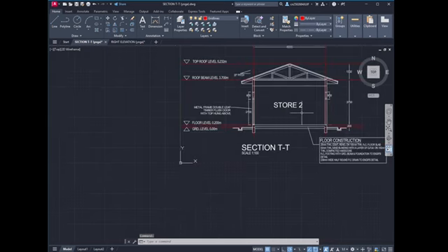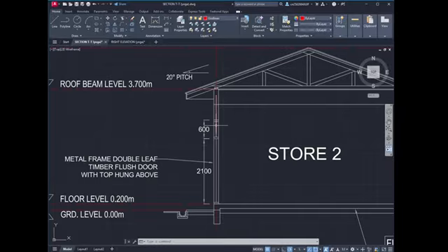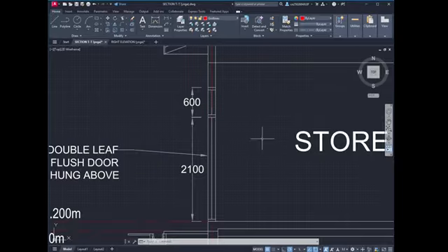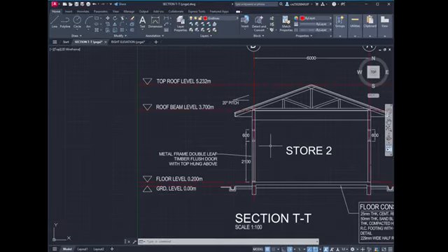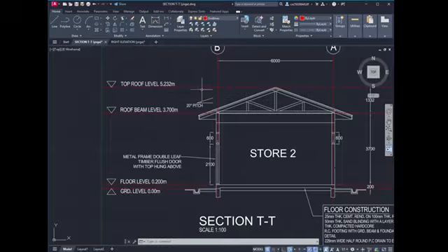Let's begin with this. I began the drawing by using the rectangle command and slowly built up from there. For every single space here, I used the offset command to give the correct size. The middle point here, I crafted by finding the middle point and just pulling straight lines. And then I found the text, and I placed the grid lines correctly from the beginning. I did the grid line before I drew the store to get the correct size and consistency for all the drawings.